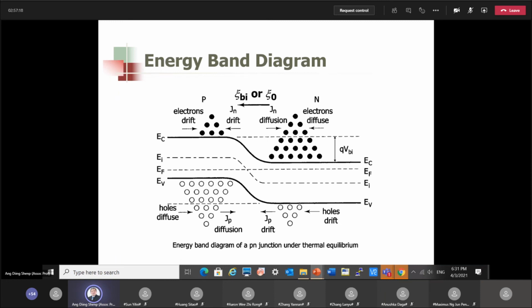The band gap is different. So because of this, the electric field would be discontinuous at the metallurgical junction. There is an electric field discontinuity present at the metallurgical junction. We will not discuss this, but essentially you can still understand the basic operation of a heterojunction.